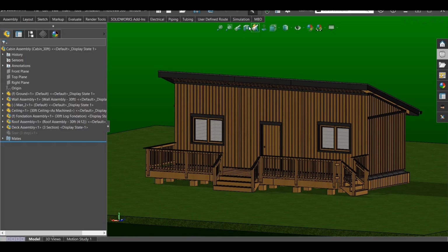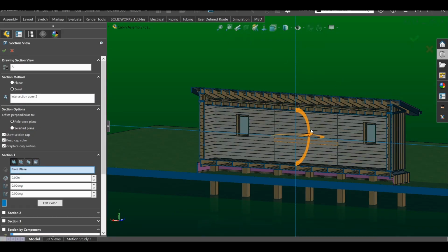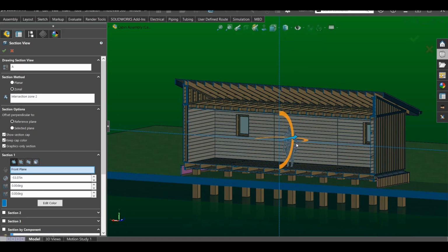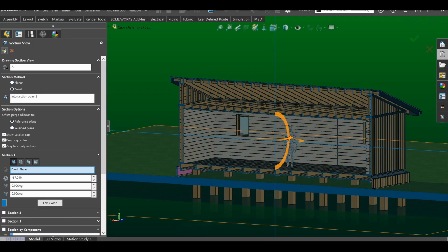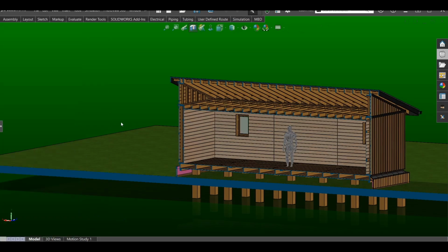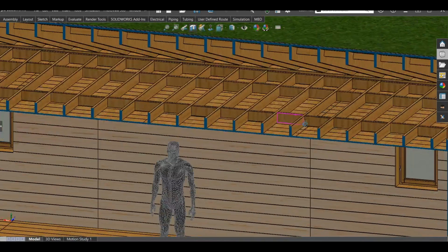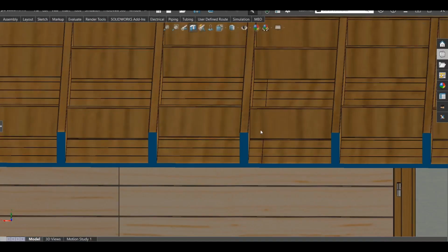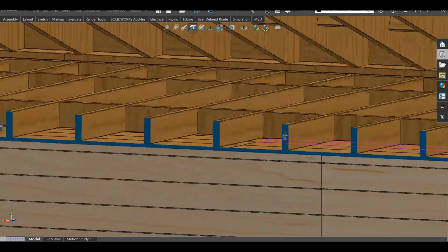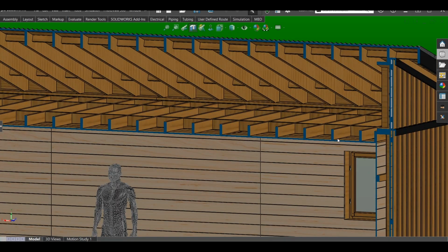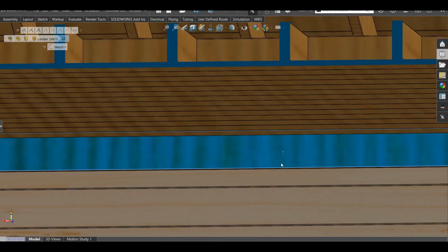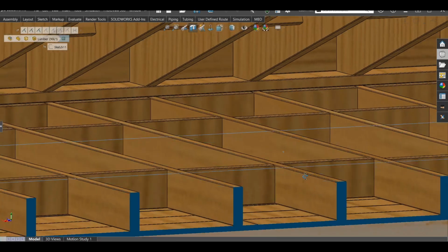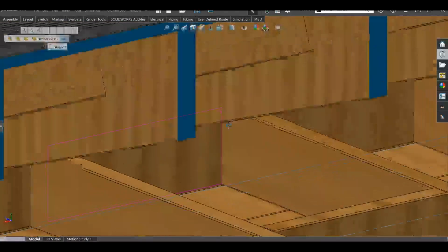So to show you the ceiling, we'll show you right there actually. Like that. So, yeah, 3/4 inch, 2x8, 16 on center. I think, is it too much? I mean, I don't know. Obviously, the board goes all the way there and sits on that 2x8 that I was telling you about, and maybe perhaps some hurricane ties and stuff.